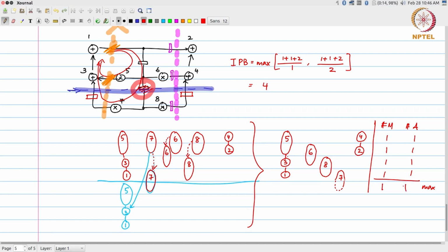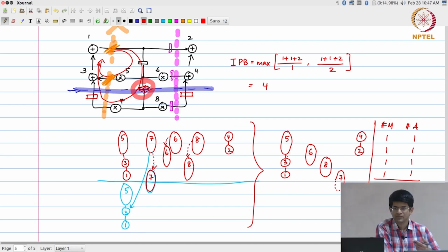We basically started out with the original biquad filter structure that people are normally familiar with. We found that that has a critical path of 5 time units. I cannot directly schedule that, and more importantly, even with 5 time units, I would end up requiring more than one adder and multiplier in order to get the behavior that I need.